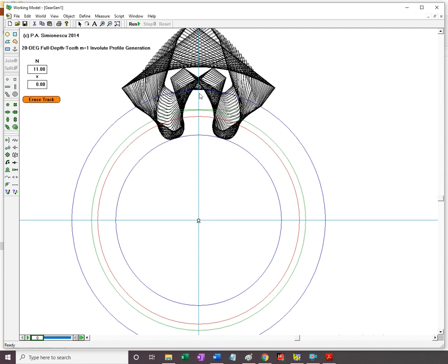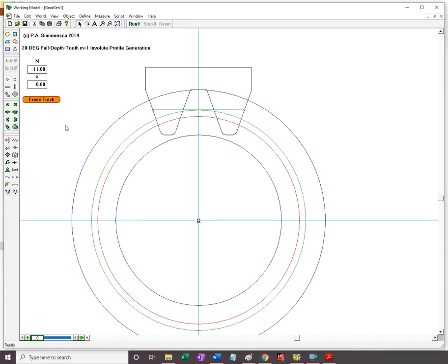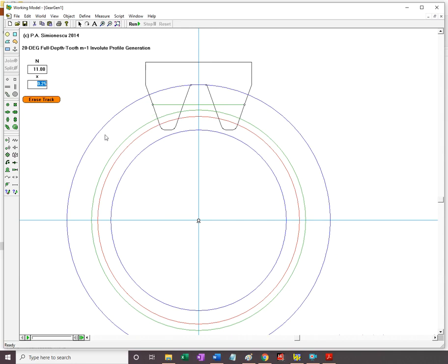So the remedy is to do what is called addendum shift. So if I make this say 0.25, what does that translate into? I have this distance added, or the rack tool is shifted out by the amount of 0.25 relative to the module.